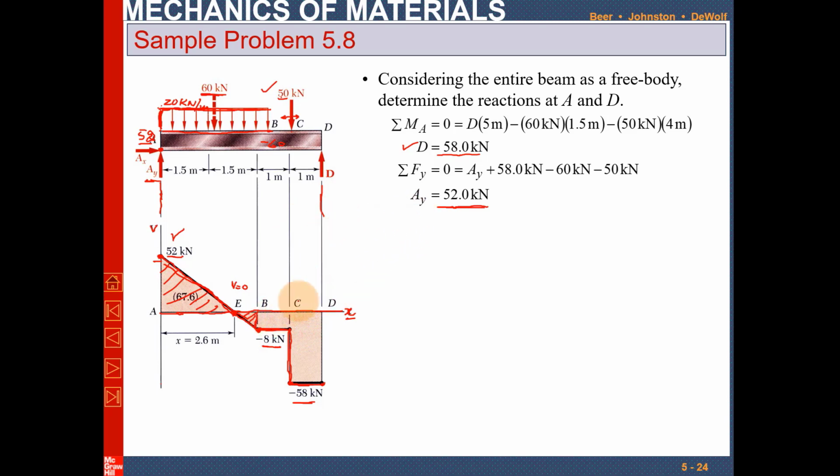Okay, so we have drawn the shear force diagram. Now we will require the maximum bending moment. We have to find the maximum bending moment. So for the maximum bending moment, we have to draw the bending moment diagram as well. So one method is either you draw the bending moment diagram, or you can use this shear force diagram in order to find out the maximum bending moment. So we will solve both methods.